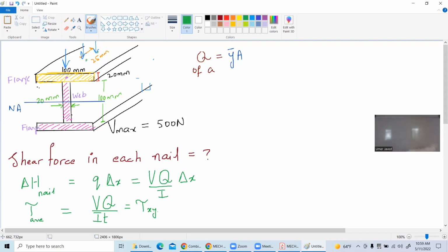Hang on. I need to answer your question. Or is it because they are in the same layer? Do they all experience the same stress regardless? I think you ended up answering the question as well, because if it's one layer, we will see that in the bending stresses, the bending stress was minimum on the neutral axis, used to be 0, maximum away from the neutral axis. Here, the maximum shear stress would be on the neutral axis, and at each particular layer, it will have a particular value. I do realize your question. I think one answer might be the one that you already answered, but why don't you give me probably a few minutes? If we finish this question, probably I can think about it.